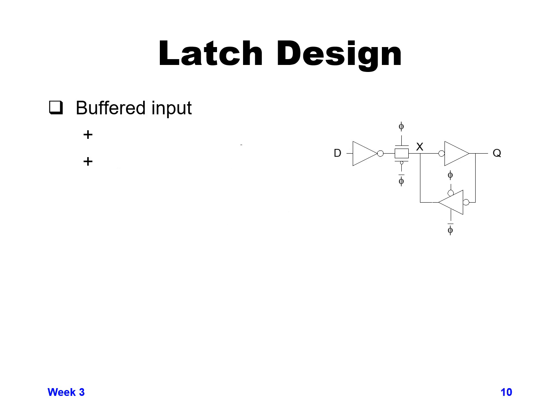Continuing on with our latch design, one additional element that we can add compared to the previous slide is an additional inverting buffer at the input, before we go into the pass gate. This buffered input latch fixes our diffusion input. Previously our data was going directly into a diffusion, which is more problematic than just being received by gates, and so this fixes that.